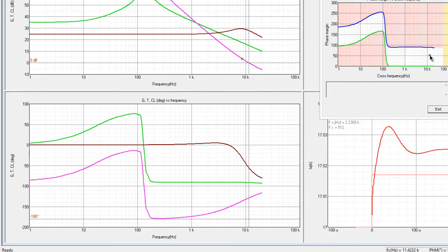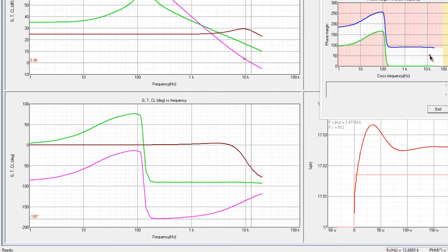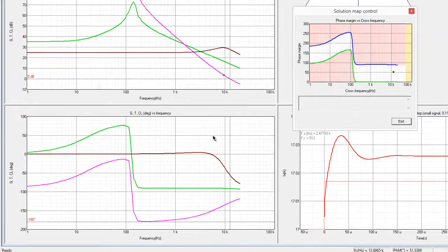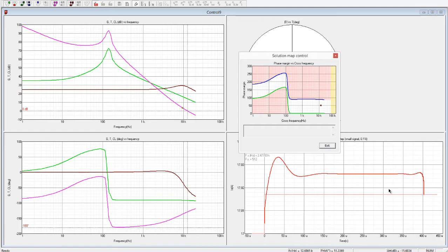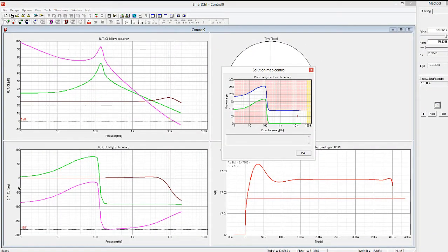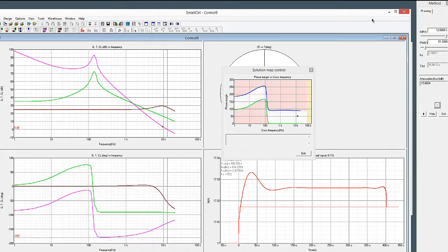So we're going to need something decently quick with not too much phase margin in order to achieve that. So I think something in there will be pretty good. This DC offset in here, we don't need to worry about. It's because we don't have a solution down to 0.1 hertz or close to DC. So this, we won't actually see a step off here. So we'll use these numbers to design our controller.